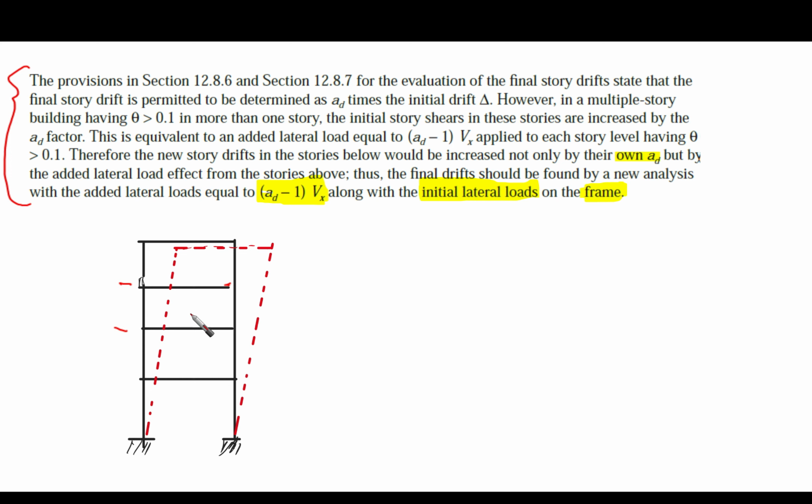in this story, the augmented base shear, or V, is going to be like V prime, like this, okay? And here we have another V, which is not augmented, it is related to the second floor. It is V2, for example, and let's assume this V3 prime, and this is like V1, for example. Here this is V3 or V prime 3. This means that we included P delta in the calculation of this base shear. Actually, it should be V3 only, without V prime. It is a little bit higher or larger than V3.